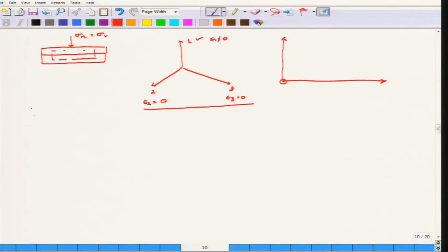both in the second and third direction due to the Poisson's ratio. So again here P will be equivalent to sigma 1 plus sigma 3 by 2, while Q will be equivalent to sigma 1 minus sigma 3 by 2. Now let us consider a Mohr circle and see how it comes out. So this is the Mohr circle.